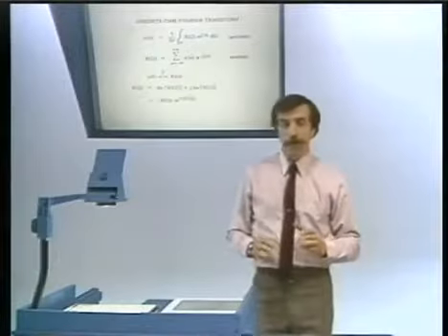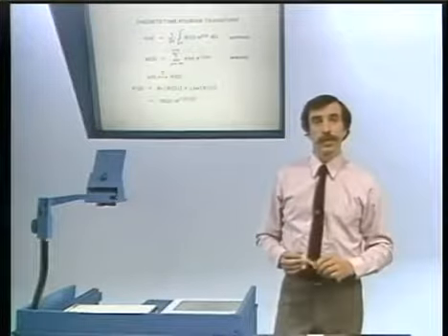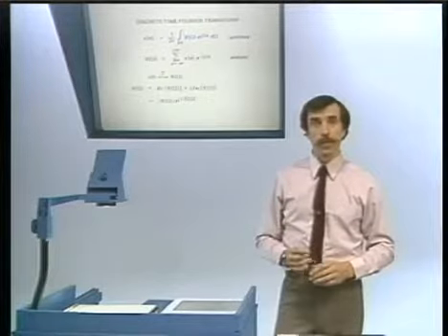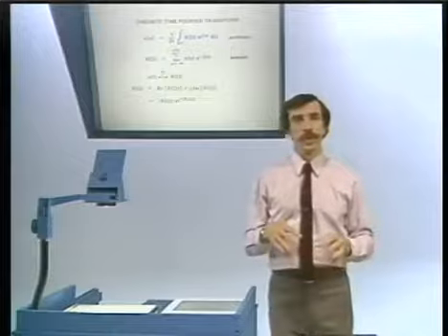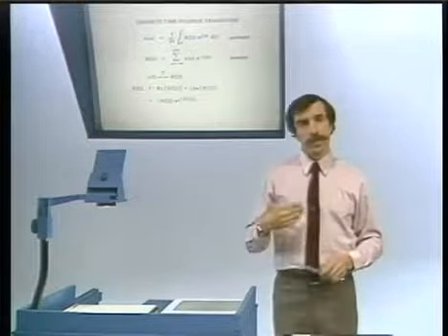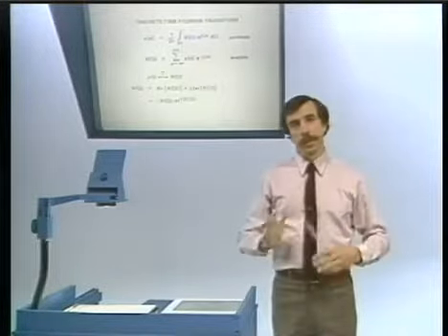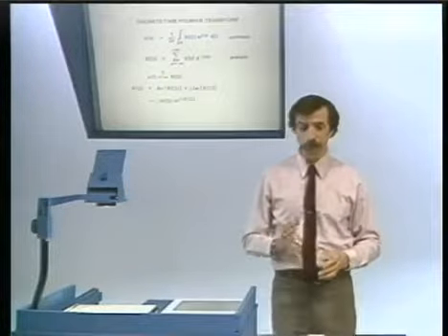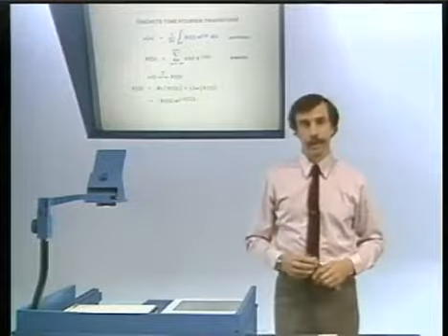Now, the discrete time Fourier transform, just as the continuous time Fourier transform, has a number of important and useful properties. Of course, as I stressed last time, it's a function of a continuous variable, and it's also a complex valued function, which means that when we represent it, in general, it requires a representation in terms of its real part and imaginary part, or in terms of magnitude and angle.